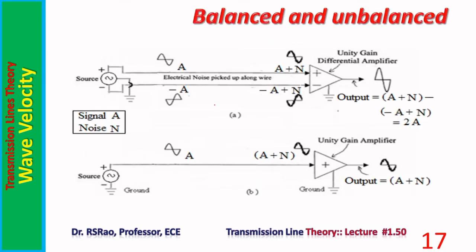Here is shown, after having some information regarding balanced operation. Now if you watch the operation of a balanced line, within no time you can catch its significance. See, this is the signal source, this is the load. Now the source is connected between these two conductors. If it drives current like this in this conductor, the current is returned through the other conductor. That's why if it is sinusoidal, it is like this, and opposite. If it is plus, it is negative on the other side.